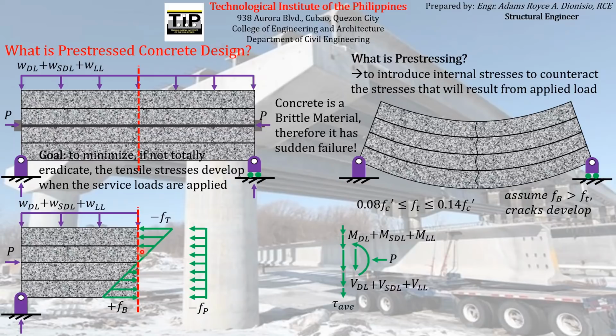So if we get the resulting flexural stresses that act along the fibers of this concrete beam, resulting from these flexural stresses as well as this compressive stress coming from the compressive force from the pre-stressing reinforcement, and we add them, the figure will show something like this. If you can imagine this is the cross-sectional area of the concrete beam, we add this stress to this stress, and then this stress to this stress, and so on, and the diagram will look something like this.